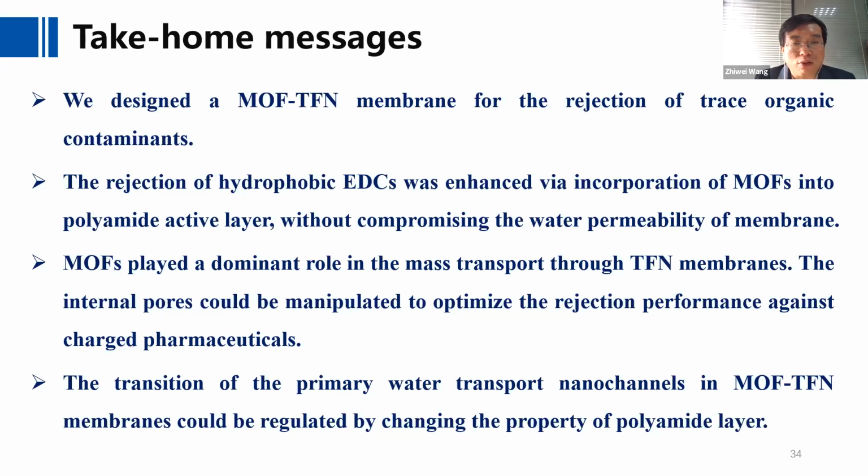The rejection of hydrophilic EDCs could be enhanced via incorporation of MOFs into the PA active layer without compromising the water permeability of the membrane. Also, MOFs played a dominant role in mass transport through the TFN membranes. Also, please note that the internal pores could be modified to further optimize the rejection performance against charged pharmaceuticals.